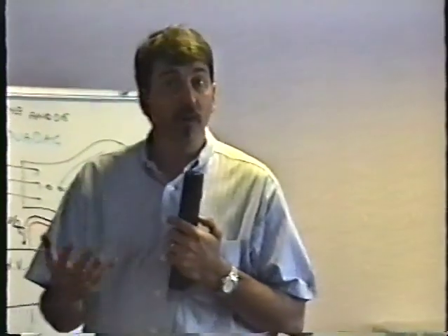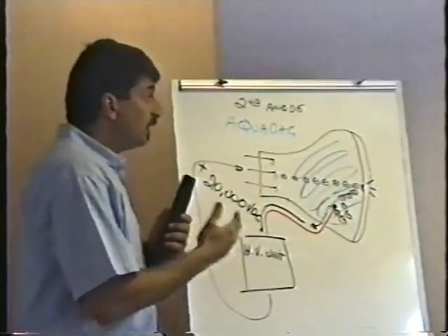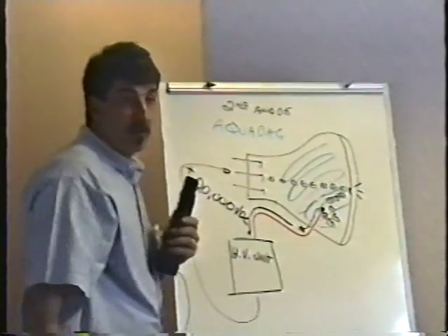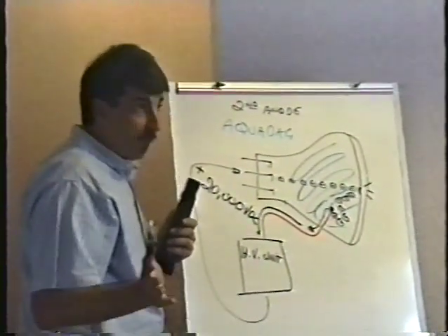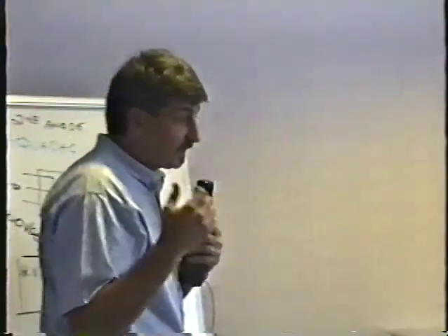If for some reason you have lost high voltage, you will not see anything on the front of the screen. If you lose high voltage for some reason, you're not going to get any picture whatsoever, because it's going to leave those electrons in the picture tube and they're going to repel the beam as it tries to hit the front of the screen, and unless it can whack it at the speed of light, just about, you don't get any picture.